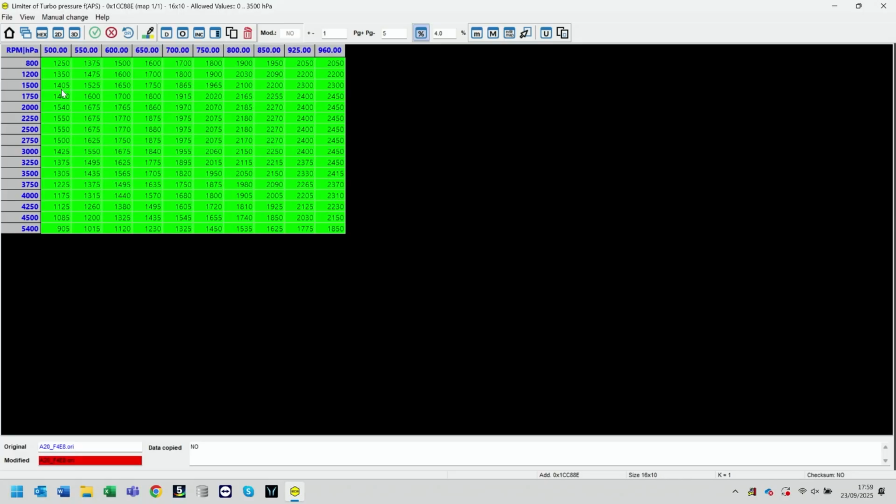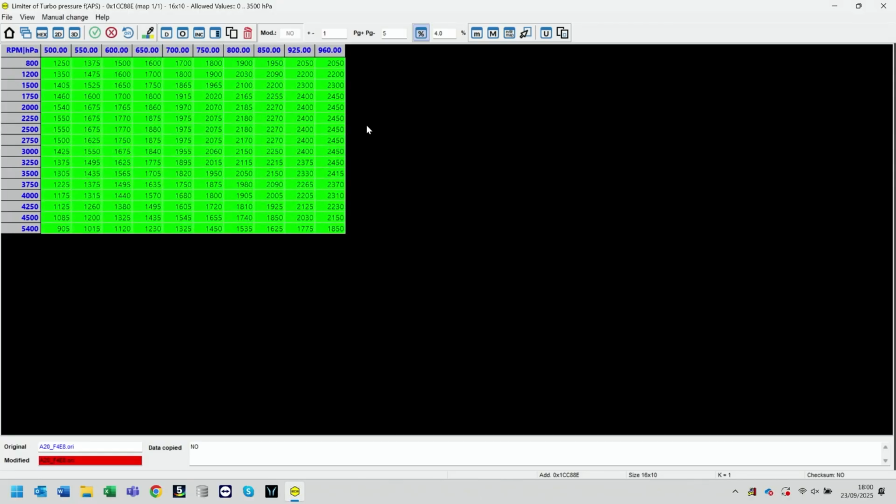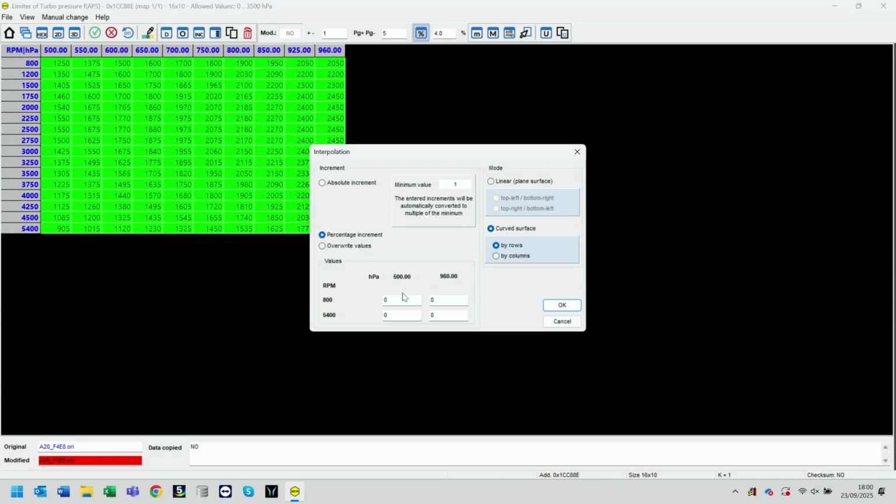Well, that's fine because we're not producing any boost below 1500 RPM. There is nothing worse than making your change and accidentally selecting 1750 and 800 millibar and actually finding your car is running down here and you haven't made the turbo change. So this is a nice safe map that we can make the change as just a flat percentage across it, 8 in each corner.